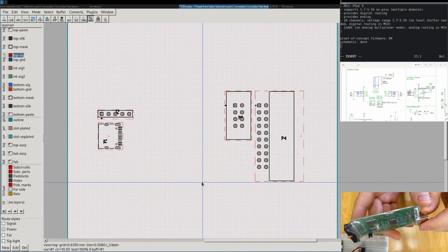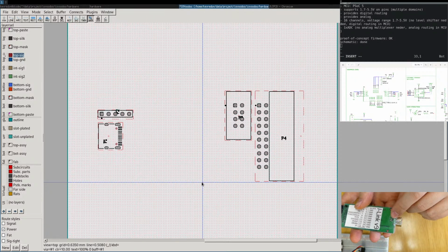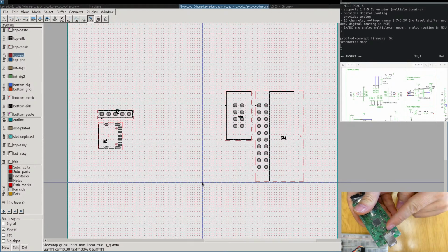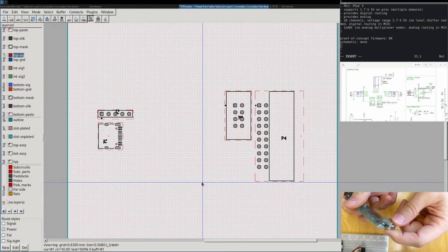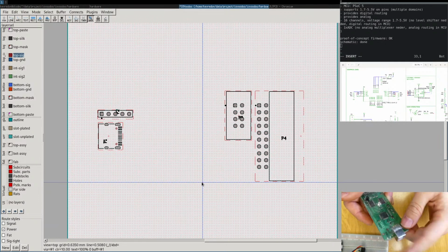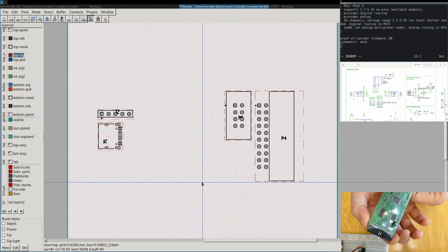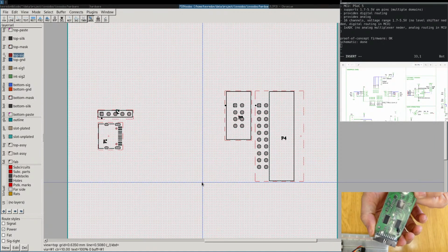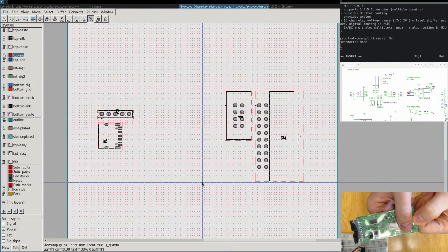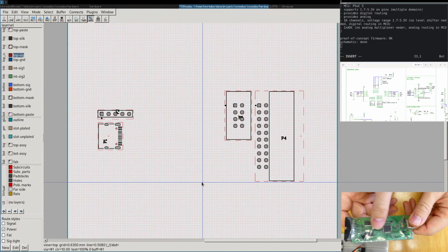As long as we don't exceed 10 centimeters, there will be no difference in price. Same here. Here they added it to the edge. They could add it a tiny bit back, so it's a bit more robust, and my connector will be more robust. But the idea is that I will have the same size as the connector, and then I will put a shrink tube over the whole device once it's finished, so it doesn't short anything by accident.